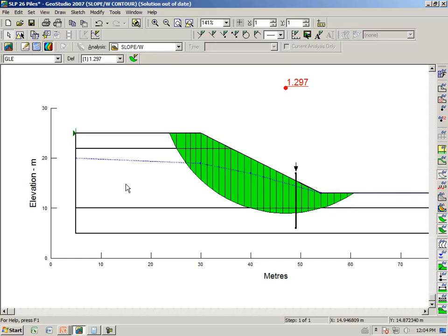Now if the slip surface goes underneath the pile or the dowel, then of course there is no force. But if it goes through the pile or dowel, regardless of the position, it doesn't matter if the slip surface is here, here, here, anywhere, the magnitude of the shear is the same. So this is a rather crude approximation, and as I have already said, the difficulty with this approach is coming up with the magnitude of the shear force that you can rely on for design.